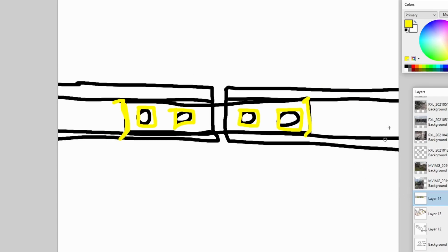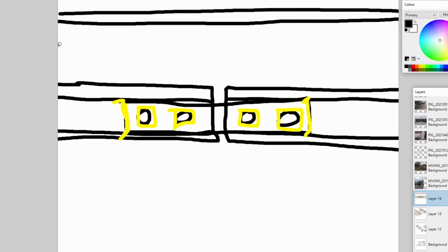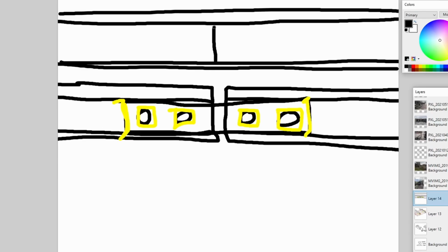In modern day, rather than using these, they typically actually do a really, really cool process where they do a thermite weld in the field, welding the 2 pieces of rail together. And so typically, when you have a thermite welded track, the train will end up seeing a continuous piece of rail, just like this, but you'll have an extra bit of thickness right here where the weld was done. And a lot of times, you'll get the welders who are very proud of what they do. They'll typically sign their welds right here. They'll say, yeah, Heiss welded that right there. Boom. So typically, they'll even put that in the side of the rail for fun.